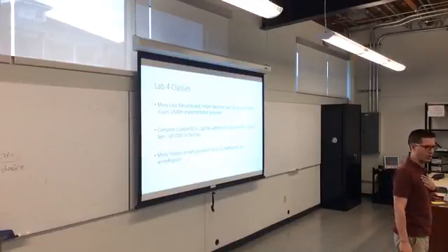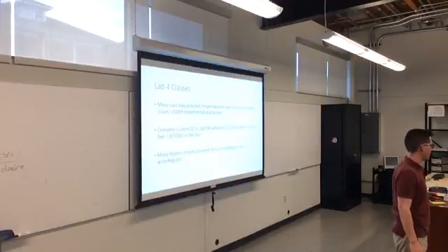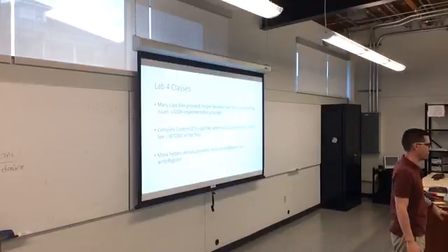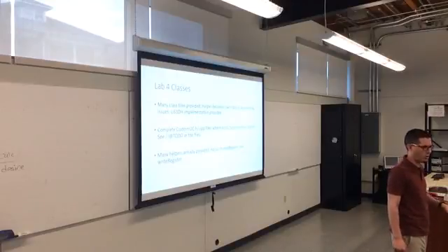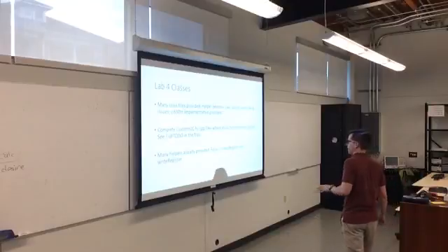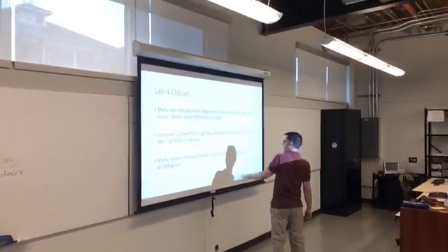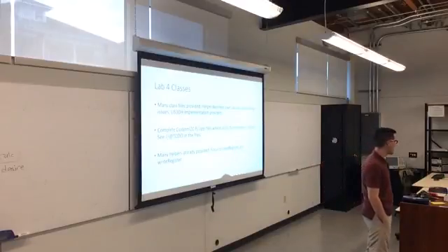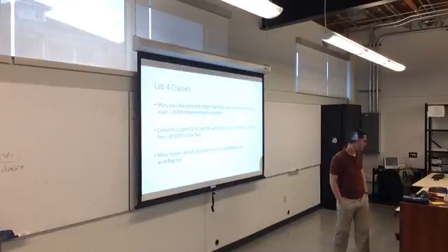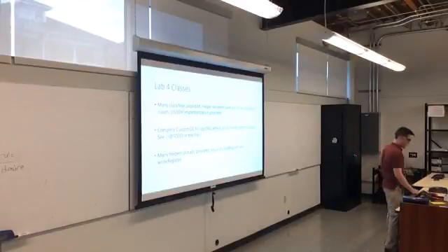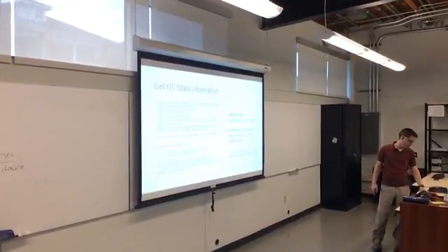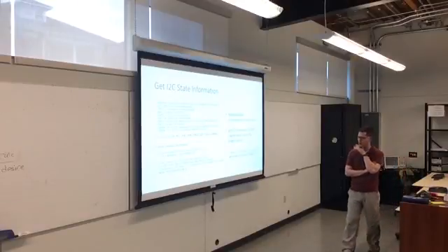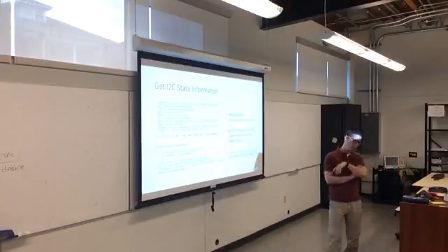The only thing that you are completing is this file called custom I2C. And so it's sort of a wrapper for the I2C data structure that we control. And there are two major functions in there called read and write that you have to implement. I have also given you several helper functions inside of that class. Because you're going to have enough trouble going through the state machine itself, I've given you sort of all the hooks to read the state